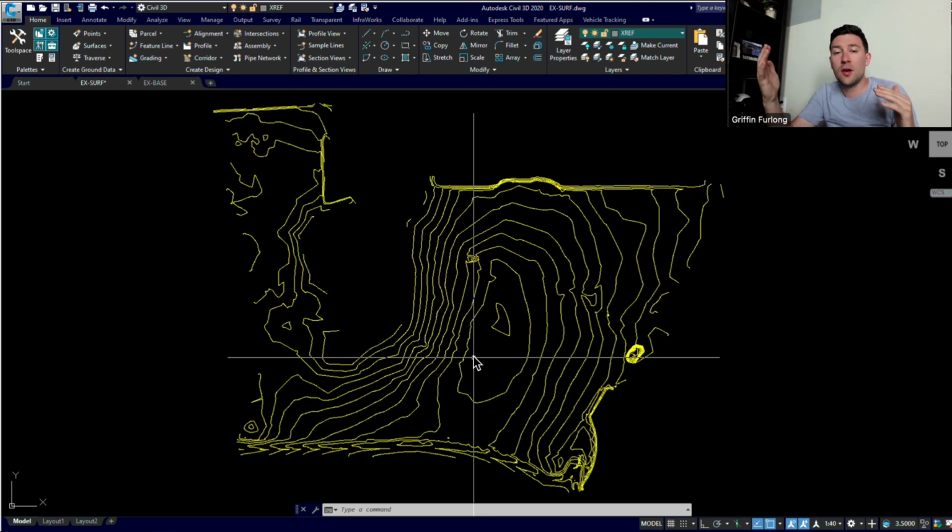Well, the tailwater is very important because that is what we're discharging against. If you didn't have some sort of tailwater, then it would be more so of a free flow condition where you are just discharging your waters into a free flow state with no tailwater or back pressure that's trying to push against the discharge, if that makes sense.